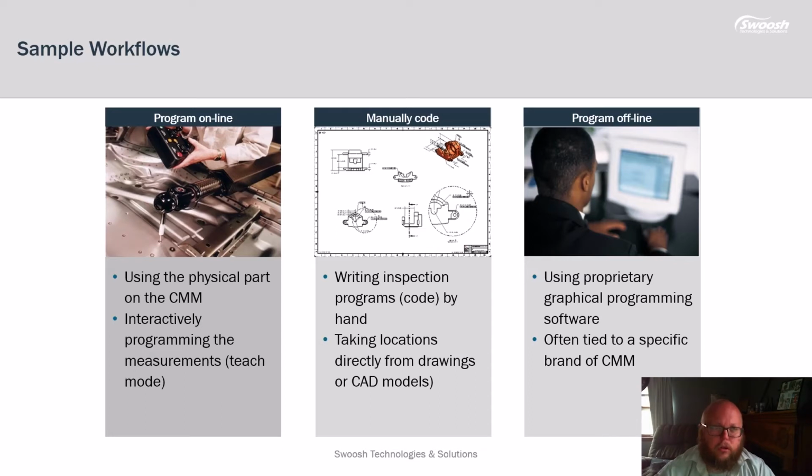So our solution, working inside of NX with NX Inspect, is going to really alleviate all of these issues. We're going to show you how we can measure off of our part geometry. We can really utilize PMI data to not only gather all the information for what features need to be inspected and how they need to be inspected and toleranced, but it's really going to drive how we program our machine.